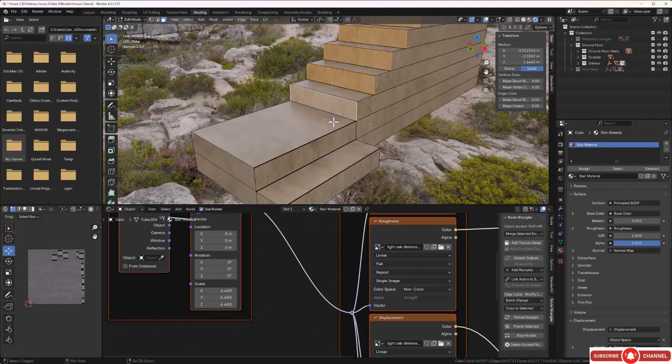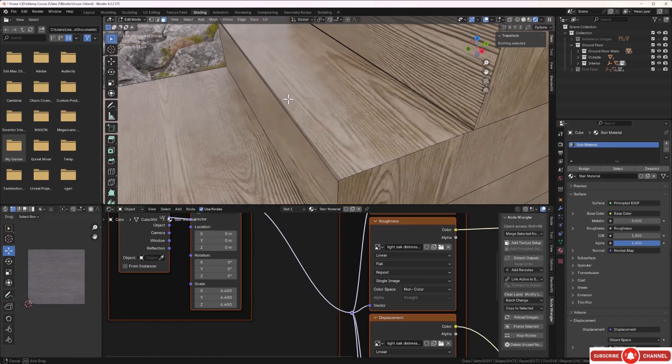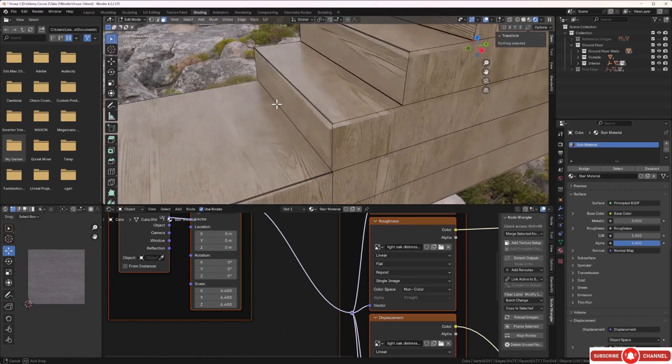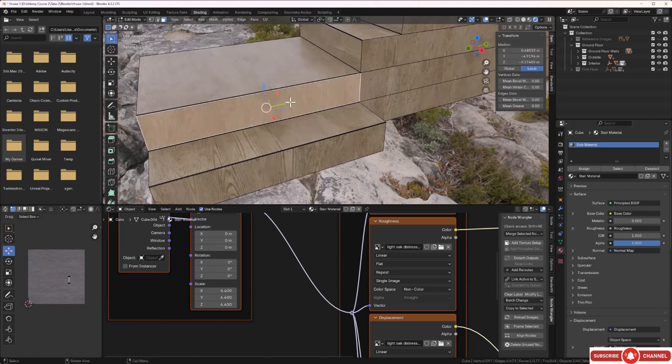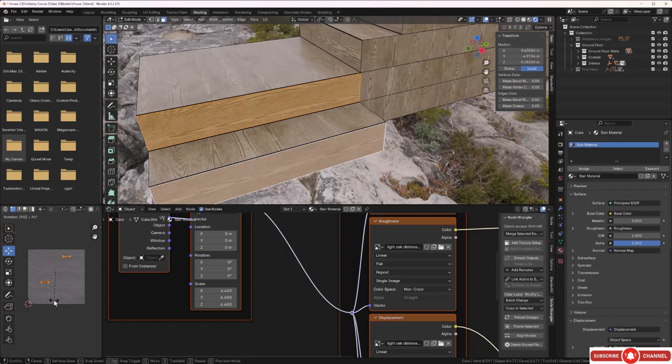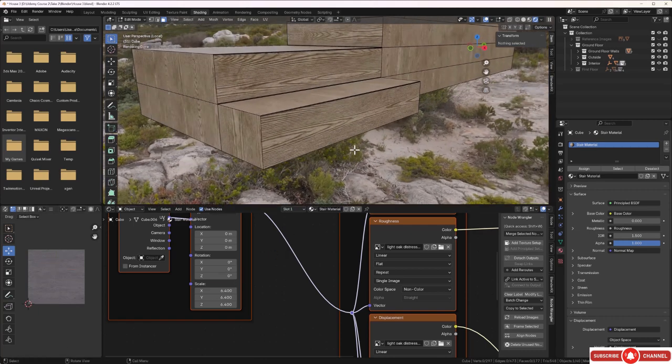And I think we'll just do those ones to begin with, and I'll grab them here in the UV map, and I'll press R and 90 and click enter. And let's see if that looks better, and that's improved things no end. That's looking good now. Okay, let's have a look at these ones and just see if we want to rotate these as well. So I'll select this one and then this one, grab the UV maps, press R, 90 and click enter. And there we go. That's altered our wood grain directions to look a little more realistic.